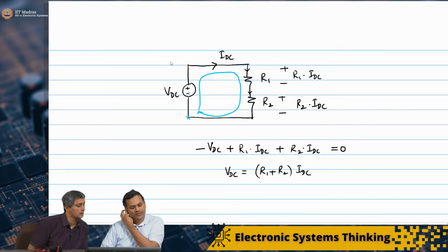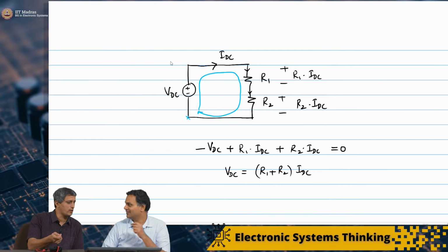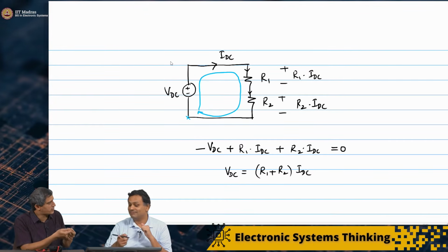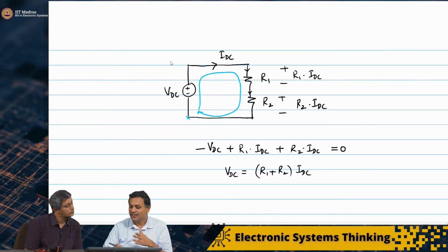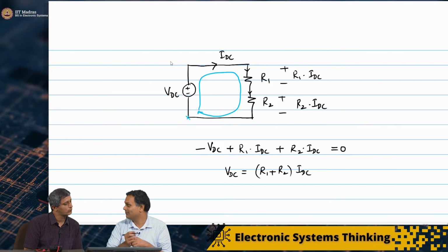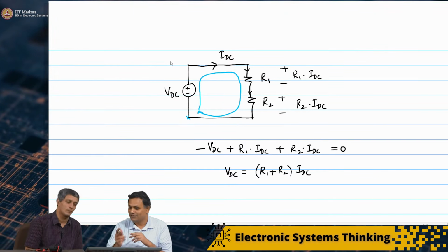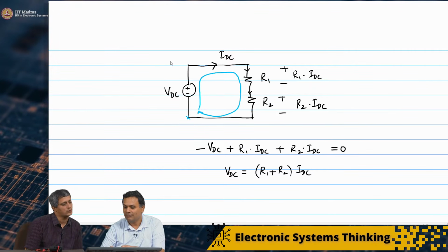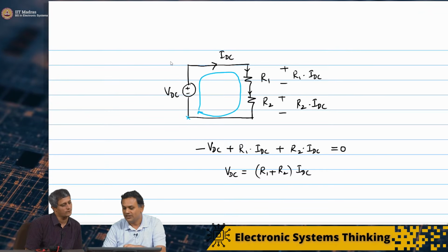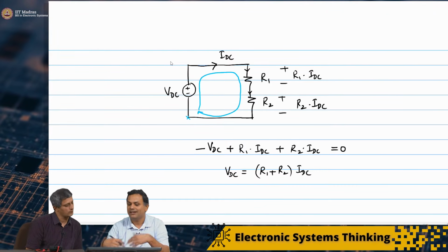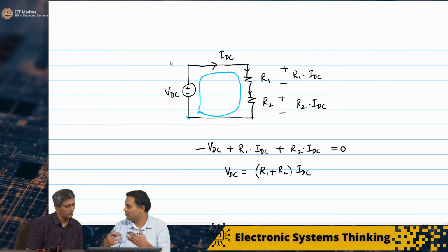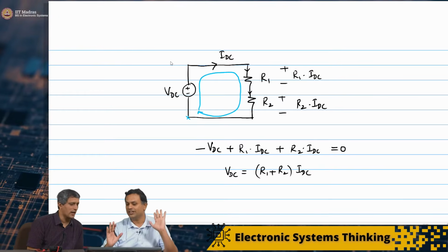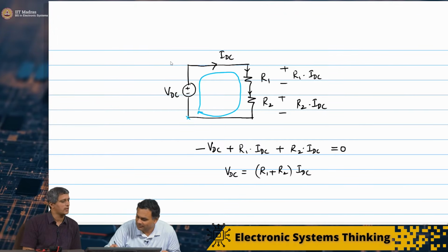Therefore, again, the multimeter all it has to do is VDC divided by IDC, and you get the equivalent resistance of that network. If I were to plot this, it also seems to be a straight line. So even for two resistors placed in series, this seems to be valid. If I used one VDC and then increased it, IDC would also increase. If I double VDC, IDC would double, and so on. For any voltage, you'll get a corresponding current. So maybe I'll write it.